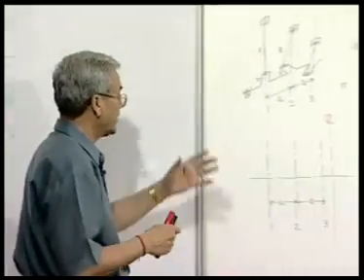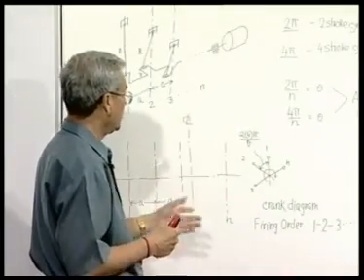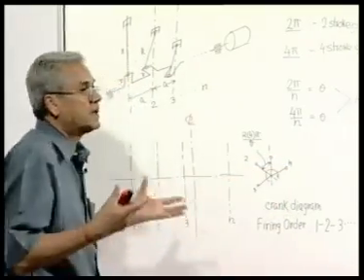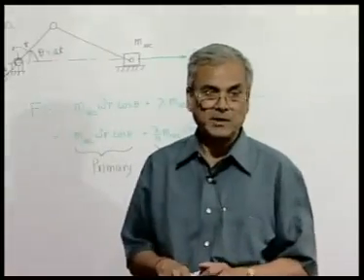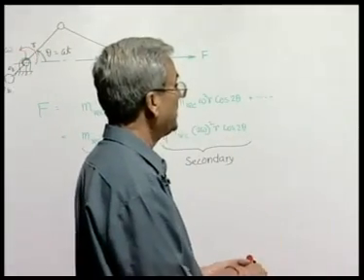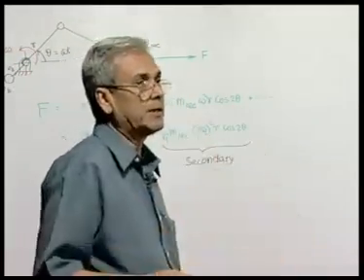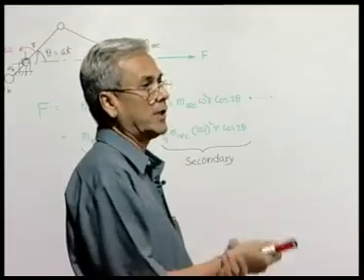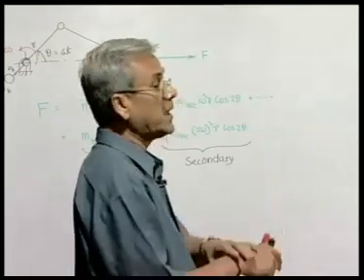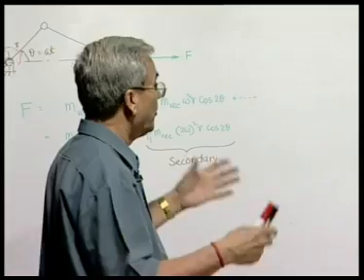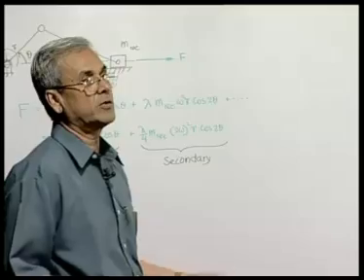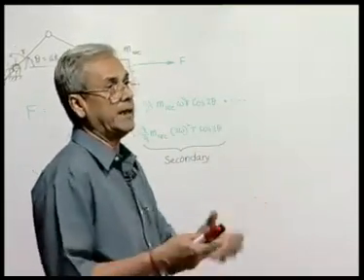To investigate the condition of balancing, we will now place the masses at the crank pins and see what state of balancing it produces. If we find that those reciprocating masses M, if we put them at the crank pins, balance among themselves, then obviously any component will also get balanced. That means the real unbalanced force also will be balanced. If the moment produced by these hypothetical masses at the crank pins is 0, then the component of the moment which will actually be there will also be 0. That means the system will be really balanced.